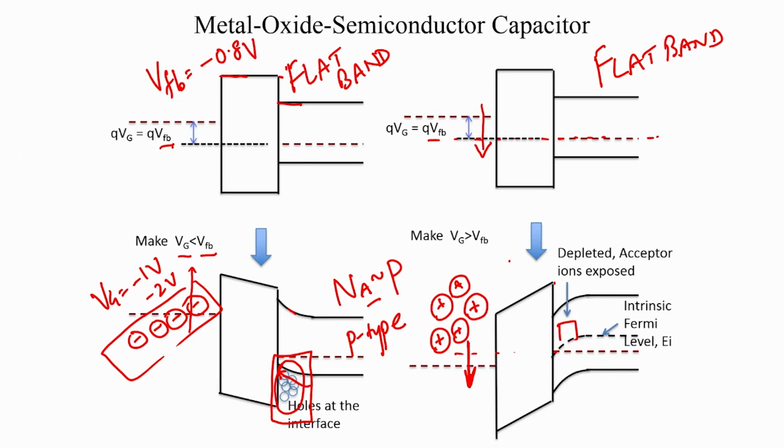So, that firstly compensates for any positive charge that you are applying on the gate. And this bending of the bands begins to encourage the negatively charged electrons to appear at the interface. So, you have two potential mechanisms, the negatively charged electrons and the negatively charged space charge, which is the fixed acceptor ions in the semiconductor, that can balance the positive charge on the gate.